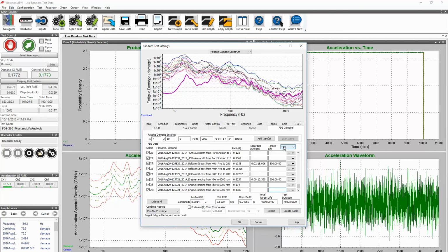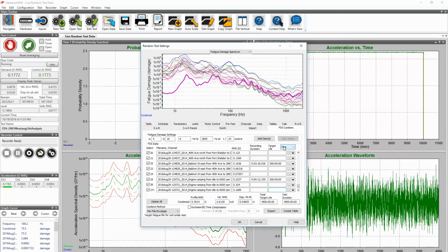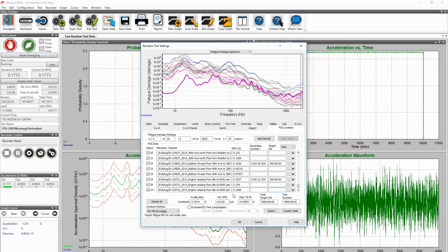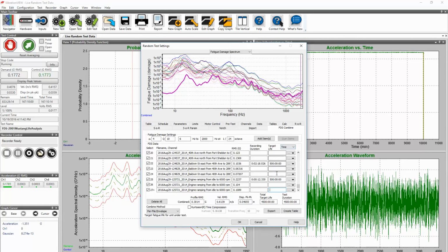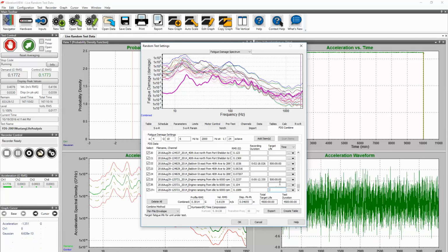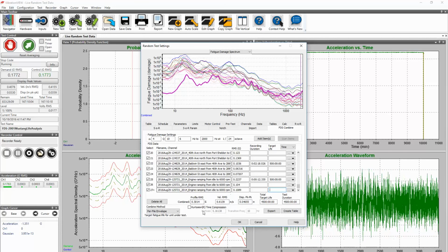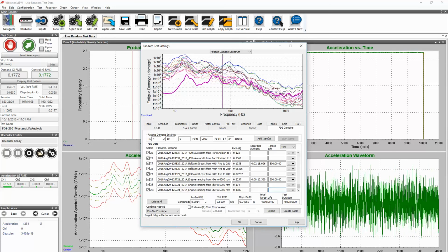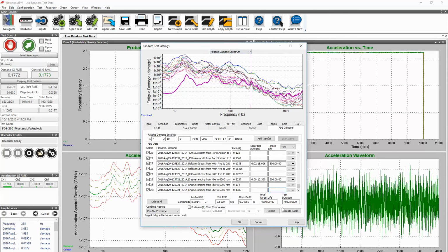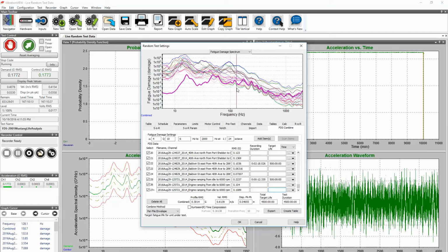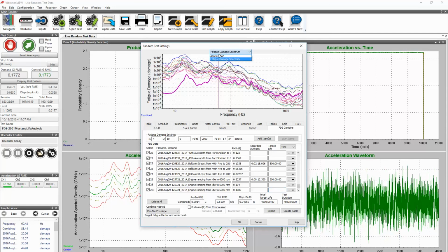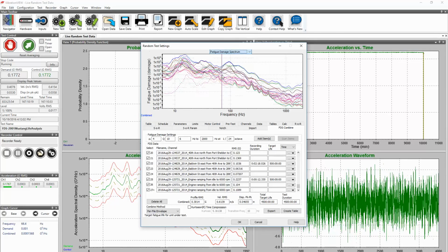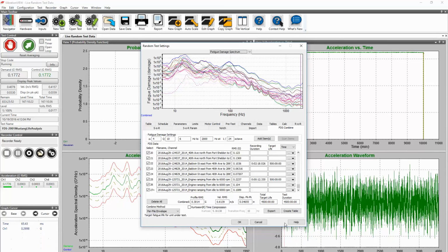So we have these same situations, put 500 hours in for each one, and then come up with a total damage for each one. So you can see that now that I've put 500 hours in, it comes up and says run this profile that is 0.3014 G's RMS. And if you run that for 4,500 hours, that will be the life of your product. And here is what your acceleration profile will look like. Back to the damage world, and that's what it looks like.